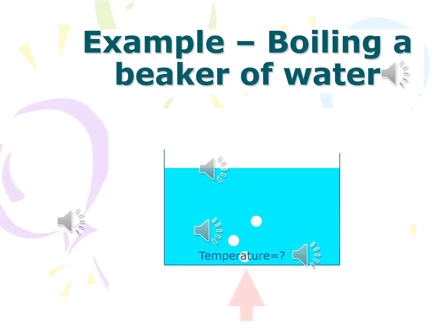As the vapor or steam bubbles move up due to buoyancy, the water streams in from the side to replace the volume. Hence you have convection heat transfer. As you saw before, this is heat transfer from a surface to a moving fluid. As you know, boiling can be quite vigorous, hence you can expect a high heat transfer coefficient.